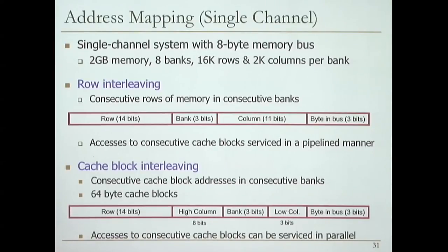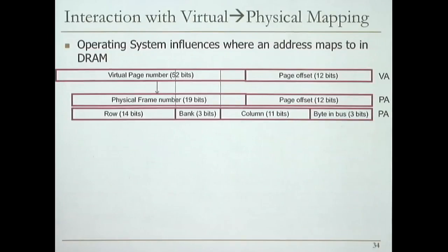So part of the cache block comes from this channel, part of the cache block comes from this other channel. Now you're completely parallel, right? So that's the multiple dependent channels that we talked about last time. They're not independent channels, but they're dependent channels. But the purpose of that is to increase the bandwidth that you get. OK, that's a good question, though.